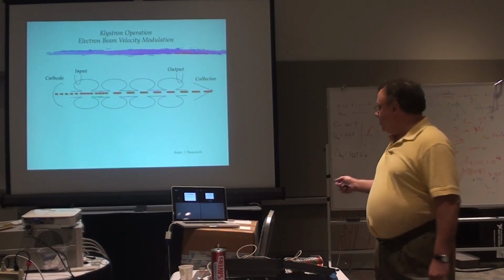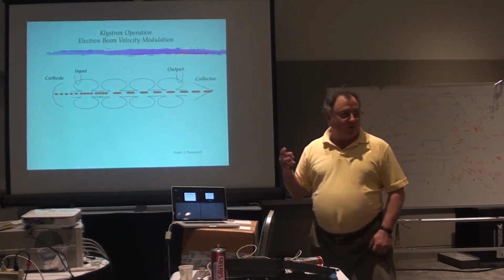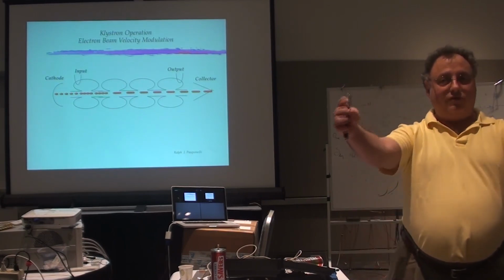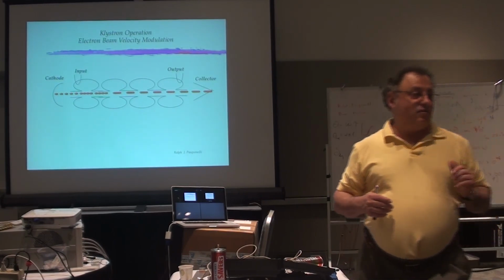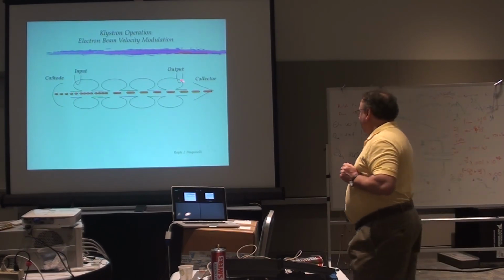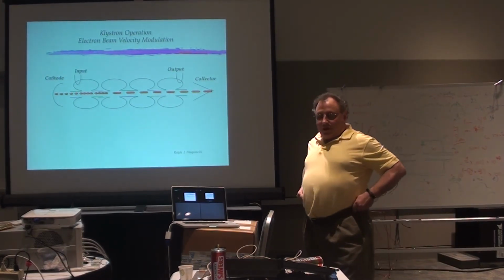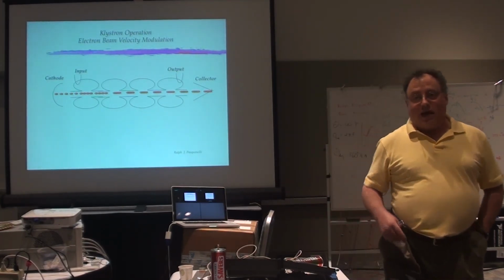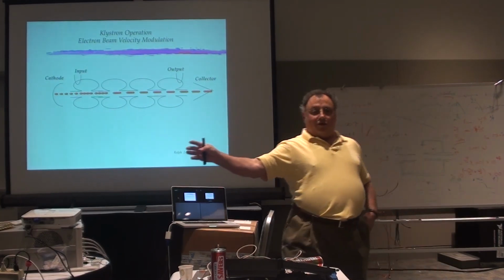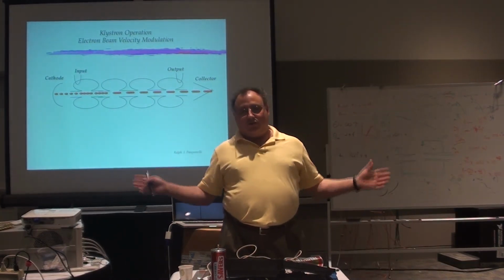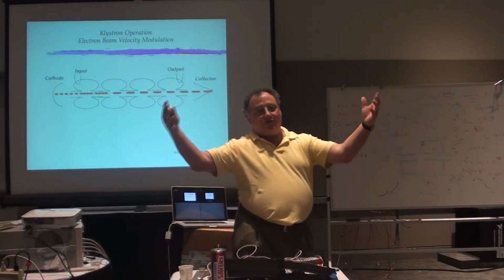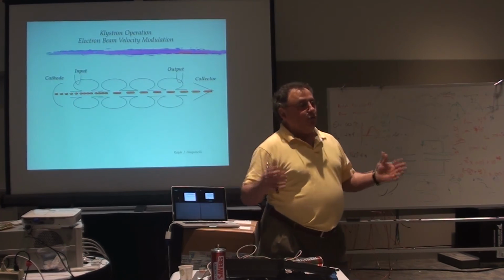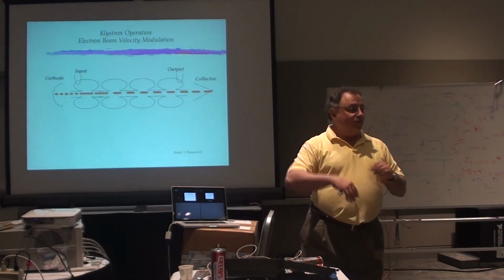But you have a window here, which is typically some kind of a dielectric ceramic window, because the dielectric ceramic window will allow the electromagnetic waves to propagate right through it and get into your coax. Problem is reflected waves. We now know all about reflected waves. What happens when you get a reflected wave is you get a voltage standing wave ratio. And so now, if all of a sudden your cavity is taking only a certain section of it, but you've generated harmonic content, those reflected waves come right back to the window, and if that window happens to be at a standing wave peak as opposed to a node, the voltage is going to go up.